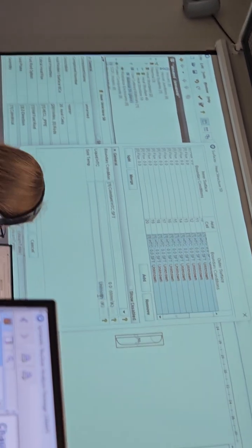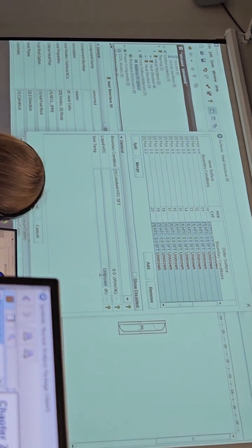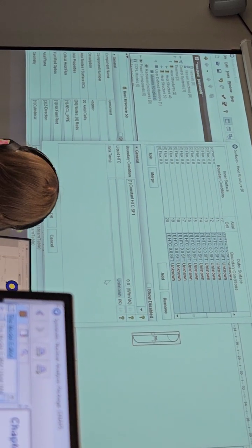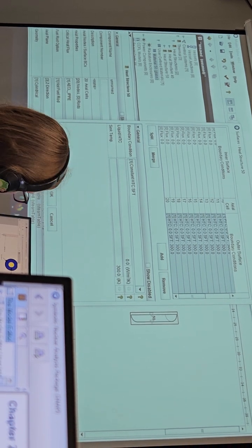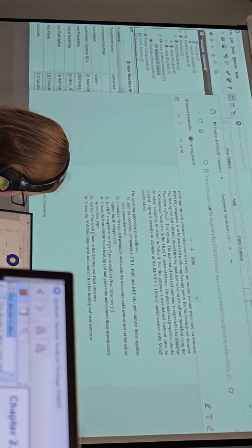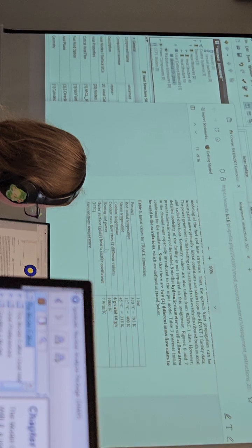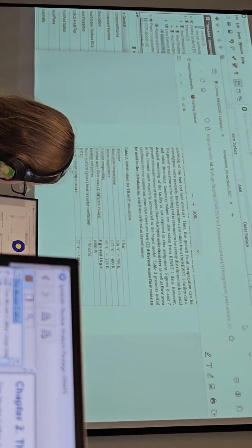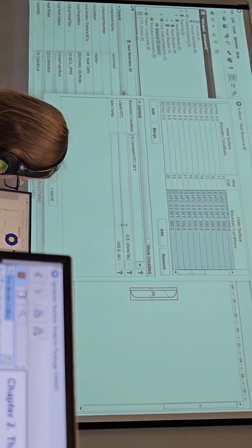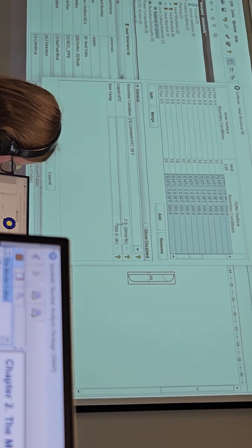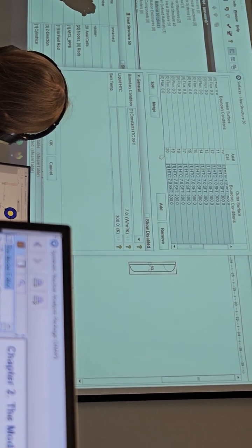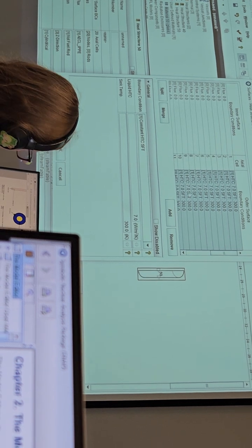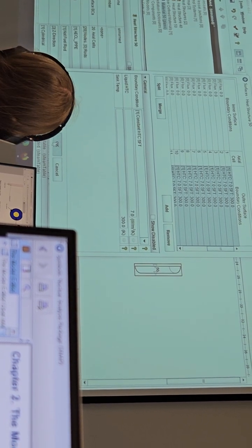So then again, sink temperature is atmospheric air, 300 kelvins. Heat transfer coefficient should be around 7 watts per meter square per Kelvin. So then we can define outer boundary conditions for all the cells for the outer heat structure. And just press OK.